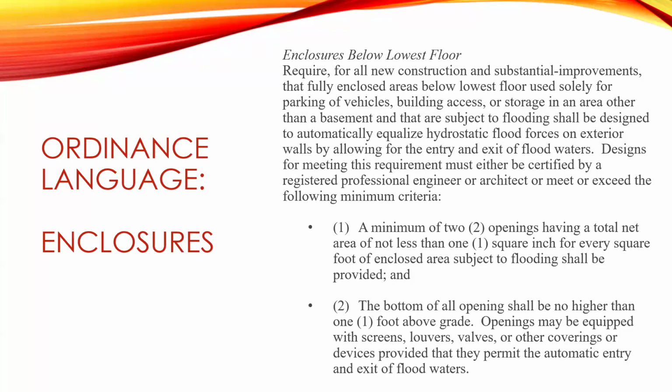So I just pulled this out of our model ordinance. It's just how we verify enclosures below the lowest floor. So this would be like a full story enclosure or a crawl space most commonly to elevate a residential structure, but also non-residential structures. So these are specific to the flood openings and what's required for that. So again, these enclosed areas can only be used for parking, storage, or building access. And this is not in relationship to any basement. We will talk about basement stuff for dry floodproofing, but that doesn't apply to wet floodproofing.